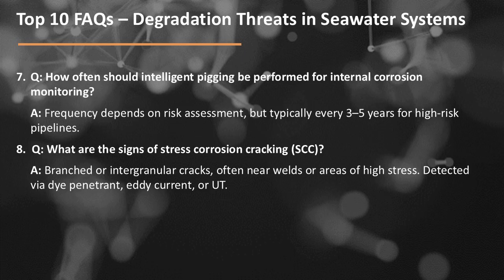Question number 7. How often should intelligent pigging be performed for internal corrosion monitoring? Answer: frequency depends on risk assessment, but typically every 3 to 5 years for high-risk pipelines.